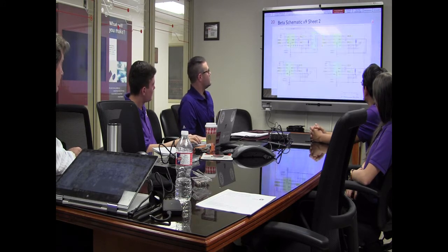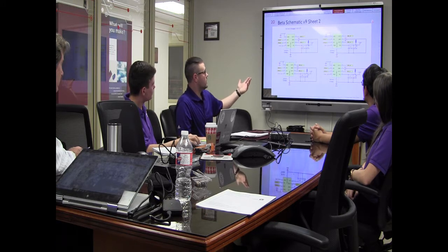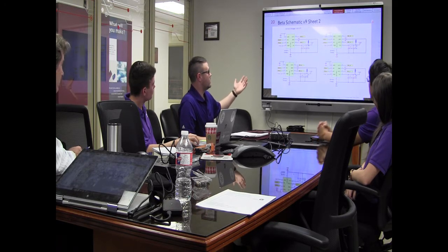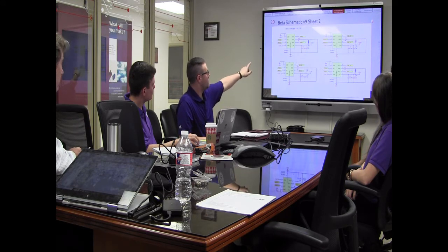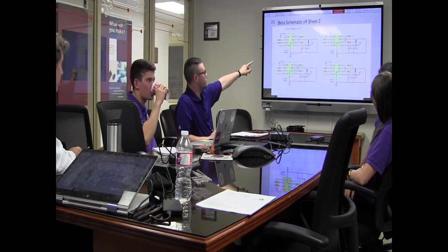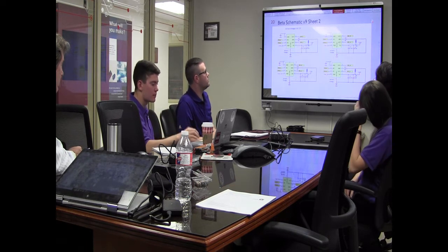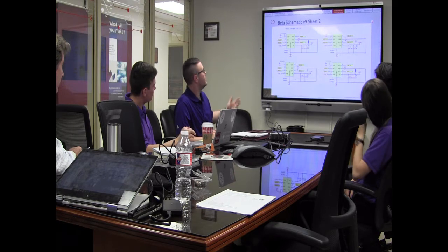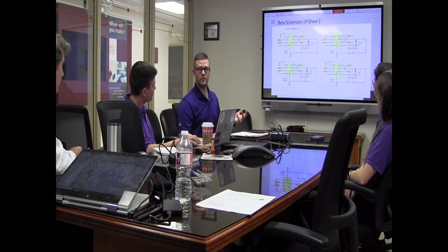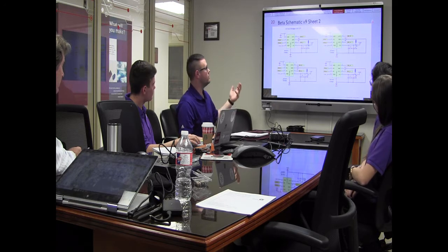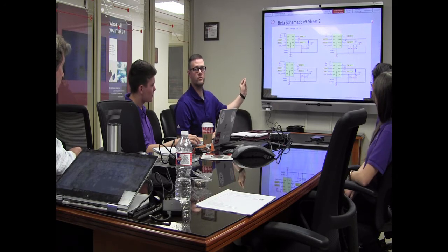No, you're good. I think it's like a 2-click kind of thing. Here's our 4 H bridges. They're in just kind of standard configuration. An important note is that there's a 0 ohm resistor on the iSense. That's because we want to use all 3.6 amps if we need to on these. If you wanted to in the future, you could replace that 0 ohm resistor with a higher value, and it would lower the output current. So if you needed that feature, all you have to do is change that resistor. But we just populated a 0 ohm for now.